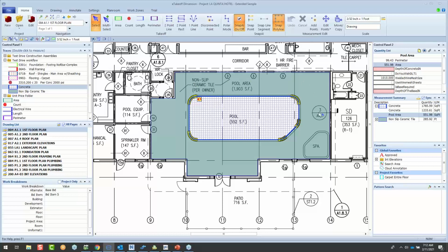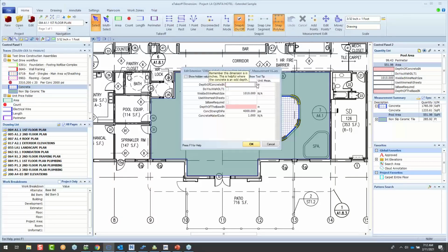So this is a basic takeoff with, if you're a unit price contractor, square foot, linear foot, that's all we need. Well, we give you that capability, of course, but we're going to give you more flexibility to adhere to what we do within our estimating system. And this warning shot tells me I have additional information to complete. So in this case, I'll go with 4 inches of depth.